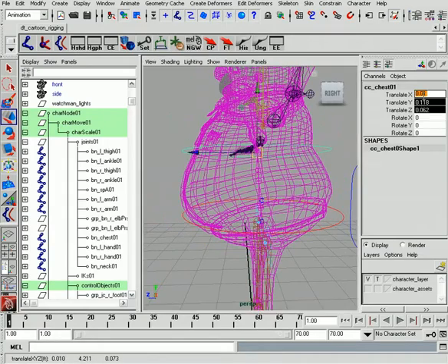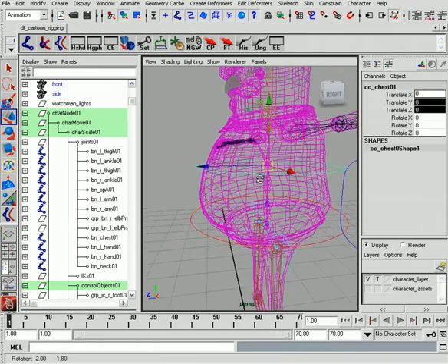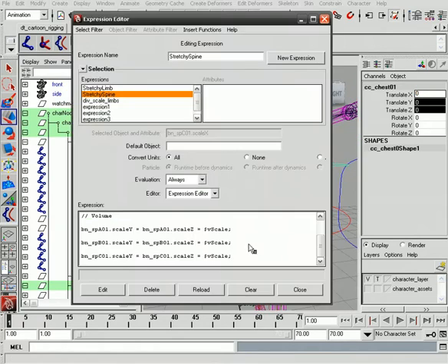Well, it's very simple. Let's go ahead and just zero out our control again, go back to our expression editor, and this is as simple as taking this number and basically taking the inverse of this number. Well, how can we do that? Well, that's going to be as simple as putting a 1 divided by the V scale for our solution that we currently have. So rather than using V scale, we'll just, again, use the reciprocal. So, again, the reciprocal is 1 divided by this current value that we have. It's as simple as that.